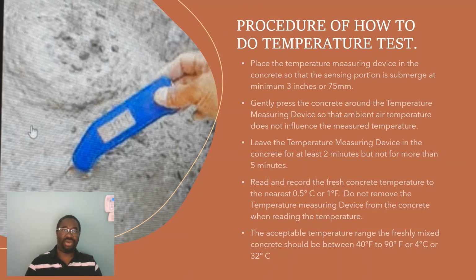In the event that you have mixed your own concrete on site and you want to do the temperature test, the same thing applies. You have to get a fresh sample of concrete and redo the test until you get the temperature reading that is within the specified limits.